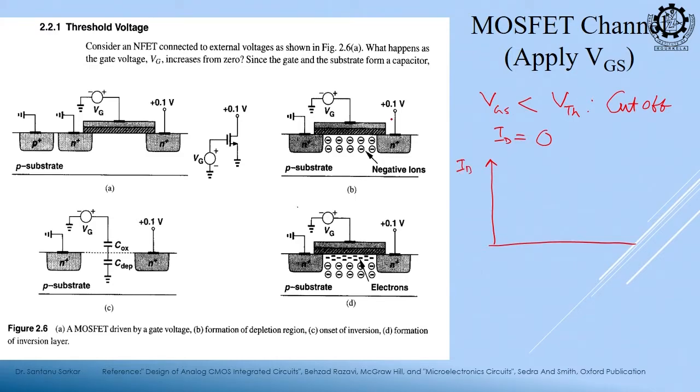Suppose this MOSFET, this current ID. So, what is the gate current? 0. Previously we had a base current, but in MOSFET there is no gate current, this is the difference. If there is no gate current, ID and IS are the same. In BJT we have the emitter current maximum; here it is the same, symmetrical. So, they look the same.